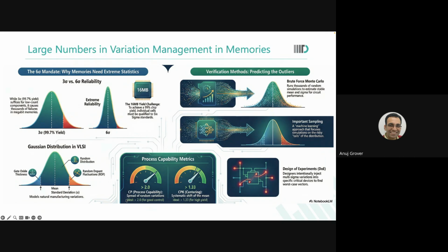Cell current is the figure of merit of the memory cell, and as a designer, that is your input. This input is not Gaussian, because the dependence on Gaussian variables is not linear. That is why verification with statistics in memories is not simply doing an SS plot and an FF plot. It can't work like that.